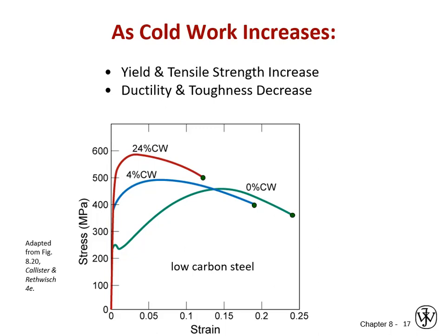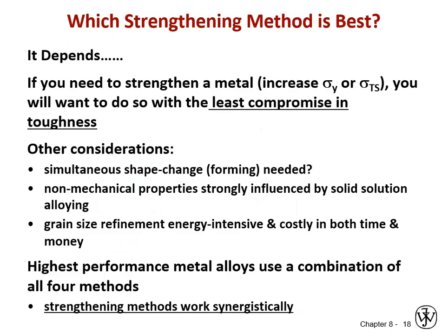So this is the most fundamental aspect of metals-based material processing. As we form a material to change its shape, to create a part, if we do it below 1/3 of its melting point, whether we wanted to or not, this is going to be the change that we have in the material properties, in addition to just the shape change of the material.